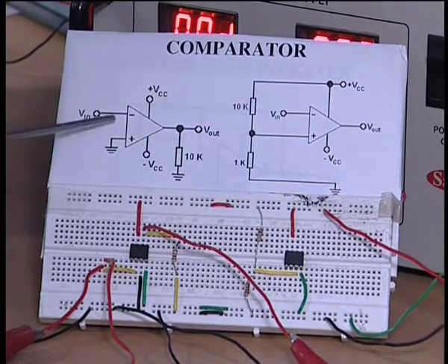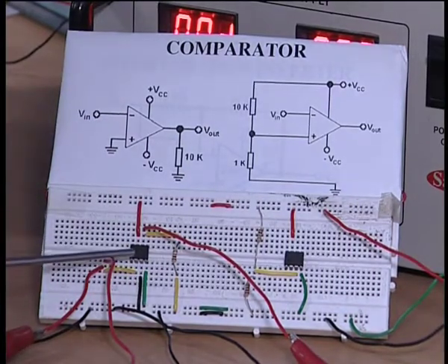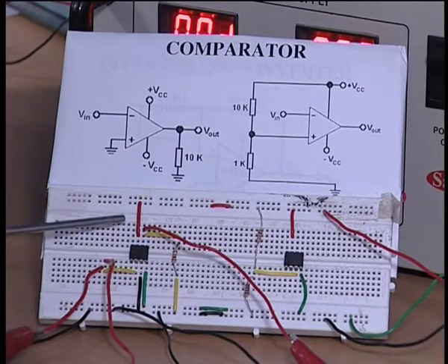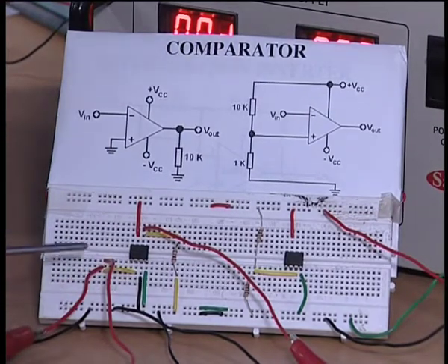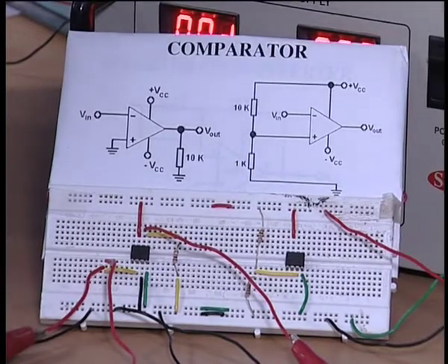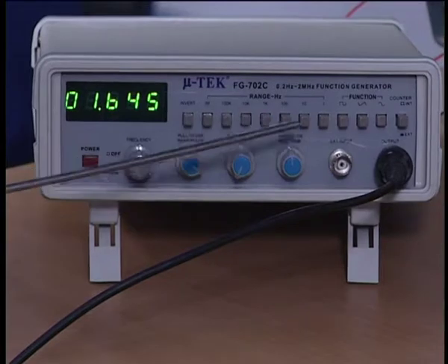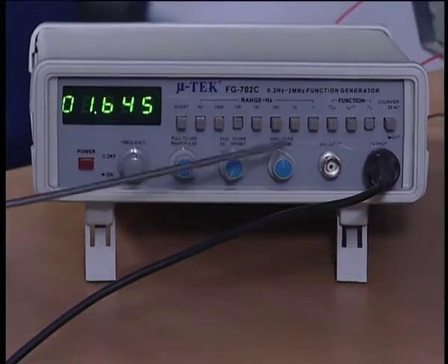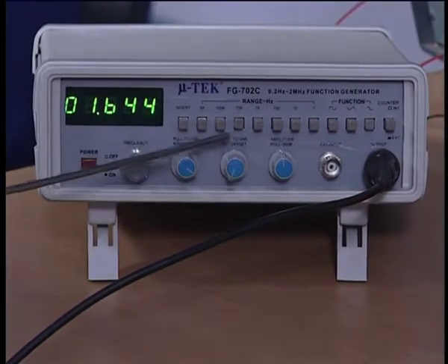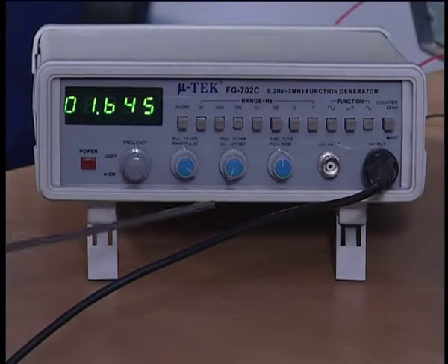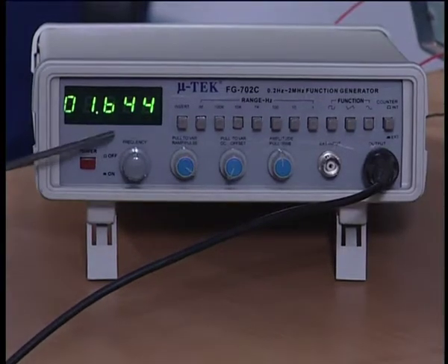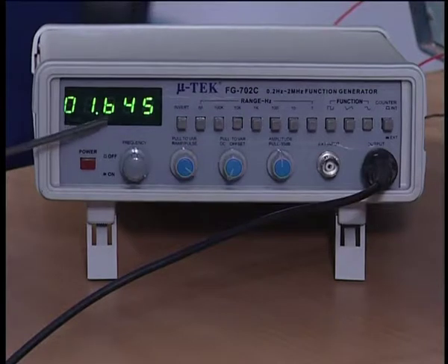Now the same circuit is put here, you can see the operational amplifier with the 7 connected to plus and the green line 4 connected to ground, and the input is connected to a function generator here, which can generate sine, square, triangle, all those things. It is put in sine mode and it is around 10k range. So this is around 1.6 kilohertz voltage.